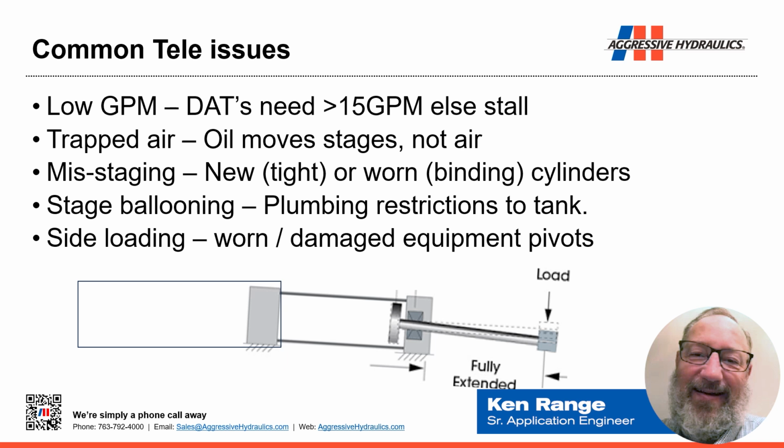It's a common thing to see when a plumbing issue exists that doesn't allow free flow of that oil back to tank. But stage ballooning at any stage, it doesn't have to just be the case. It can be the large diameter of any of the stages can cause ballooning. And guess what? That cylinder doesn't move after that happens. If the case balloons, you no longer have a seal with the first stage. If a stage balloons, it's going to stick in the head gland of the other stage. So it can be a real mess when that actually happens. But stage ballooning is not uncommon. Happens all the time.